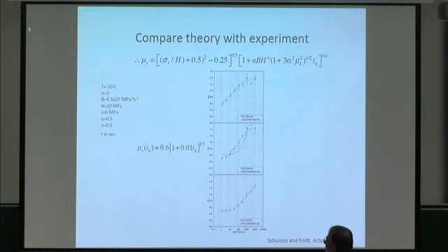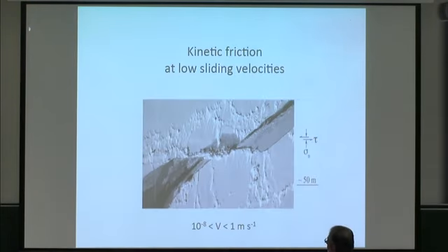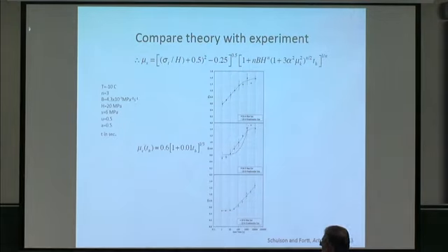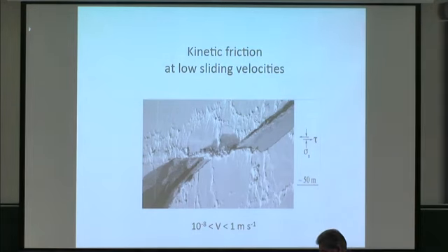Other factors in here, we had to choose a hardness. So we used one. Barnes, Tabor, and Walker again do tell us that the hardness depends on the time of loading. Well, rather than making the thing more complicated than it need be, we just chose one value for hardness, just to start it off. A hardness value of 30 MPa, I think that's what we did here. A tensile strength of 6 megapascals, which is about the tensile strength of single crystals from Michel's work so many, many years ago. Putting it all together then, one ends up with the relationship. Where do we have it?